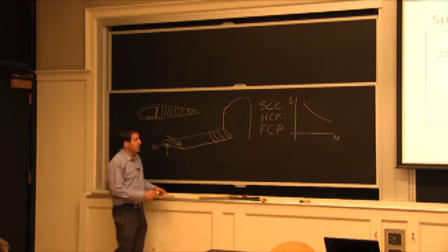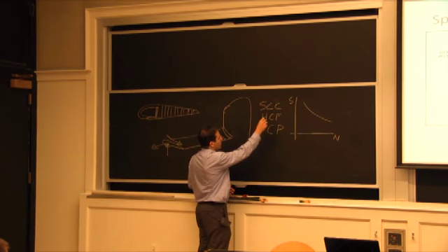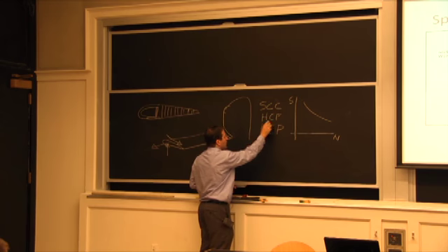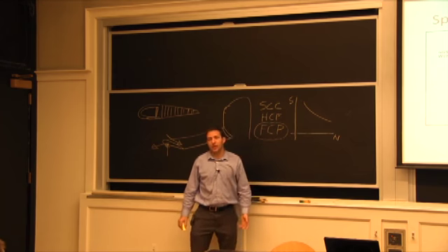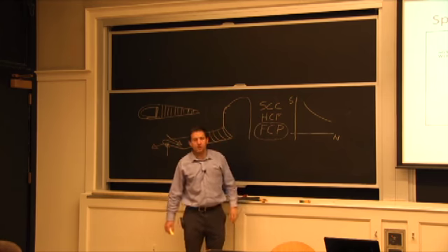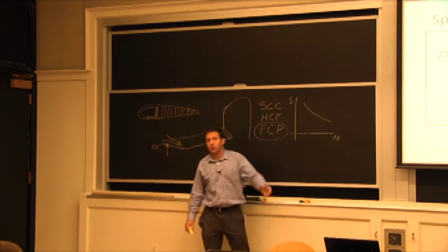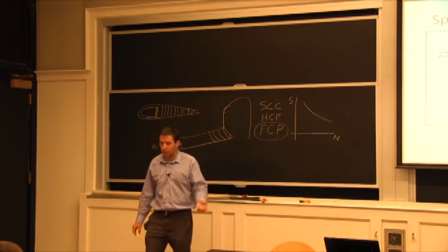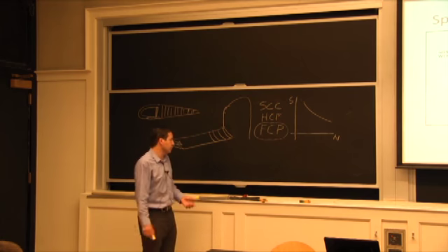Now, I should say right now that some of the designs will allow for this to happen, and it'll be only working with this. That's the damage tolerant approach. So if you say, I'm going to have a crack to begin with, you're not so concerned about the time it takes to start your crack in this kind of framework. You just say, I have one to begin with. I don't want it to grow more than a certain amount. So we call it a damage tolerant approach.